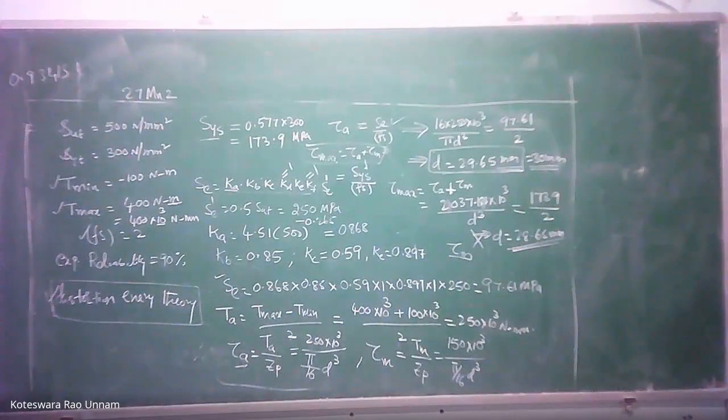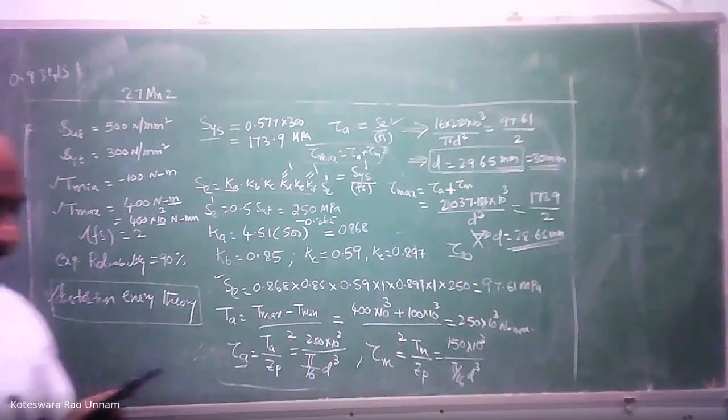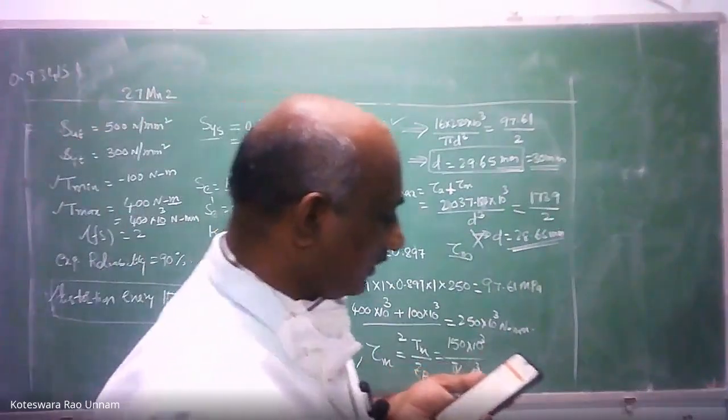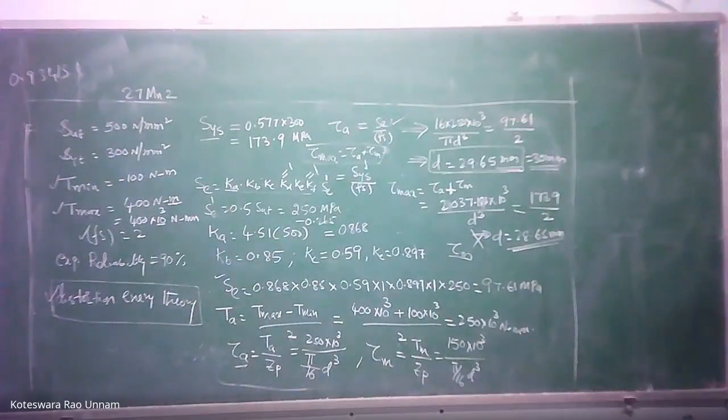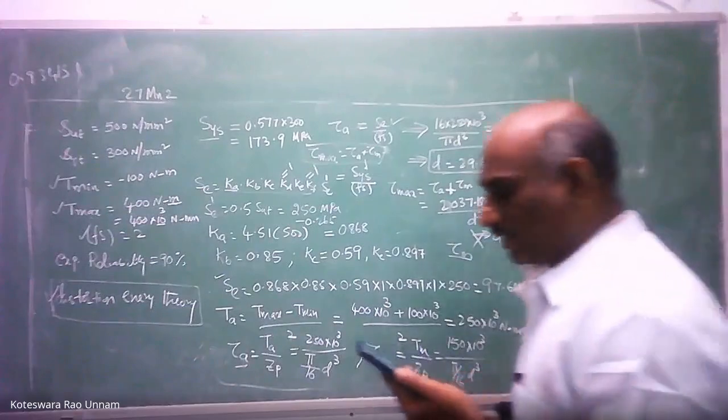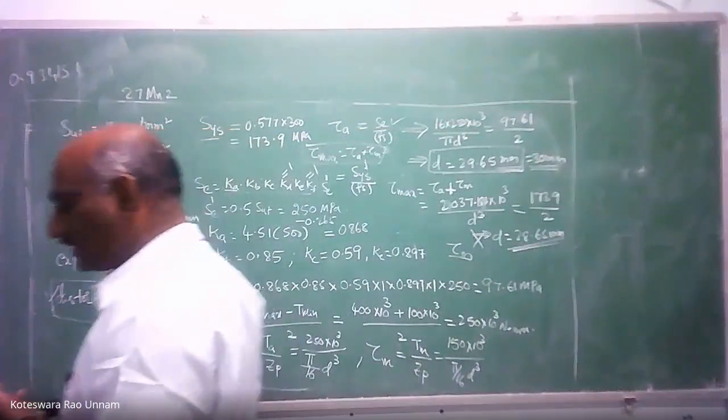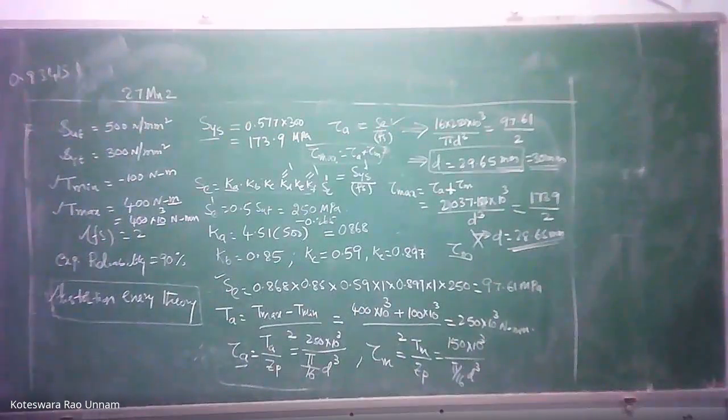The outer diameter of the bar is 30 mm. The ultimate tensile strength of the bar is 1250 MPa. The endurance limit in reverse bending is 600 MPa. Find the maximum force that the bar can carry for 10 power 5 cycles with 90% reliability.